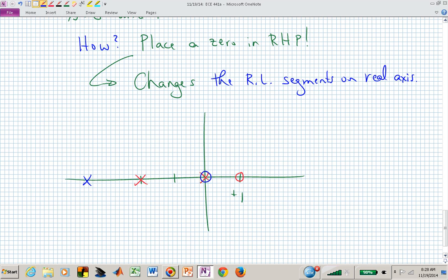So now the reason we can't do that is I have basically told you that you cannot cancel poles and zeros on the imaginary axis or in the right half plane. Given time will show that there could be a transfer function between a disturbance and the output, the reference and the output. One of those transfer functions will give us a pole at the origin. And then if somebody gives you a kick or a constant, that's going to cause the signals in your system to go unbounded because it has a fixed pole at the origin. So that's a no-no.